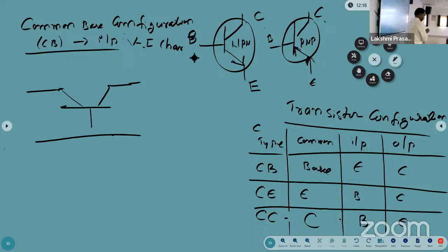Okay. Now, what devices are required to get the characteristics? Voltage and current. How can you measure the voltage? Voltmeter. How can you measure the current? Ammeter. Now you can connect the ammeter and voltmeter here. Okay, next. Now, how can you measure the current? So, how can you connect the ammeter in the circuit? See. So now here you can connect one ammeter.